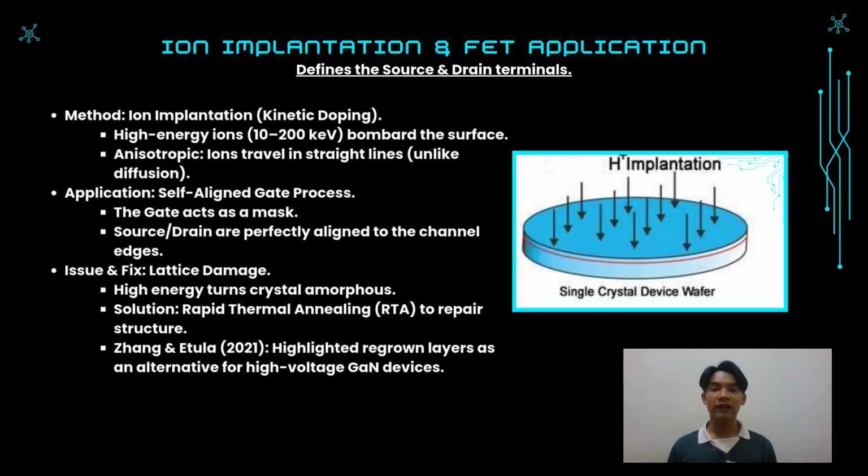However, this violence damages the crystal lattice. As noted by Zhang and Etula in 2021, while we can use regrowth techniques for special high power devices, for standard processors, we must follow implantation with a heating process called annealing to repair the crystal structure.